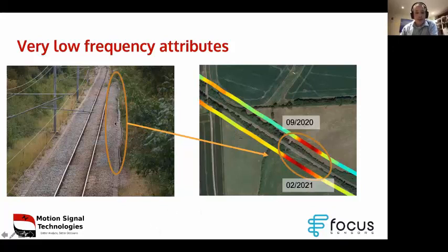And this is a photo of the section of the track. I believe this is the cable trough where it was deployed, going down the side here. I think it's fairly clear that this was not built with this rather crooked line. It was almost certainly built with a straight line going down the side. What's happened is there's some slope stability and some ground movement happening along here, and this is something we're picking up in these really low frequency signals.